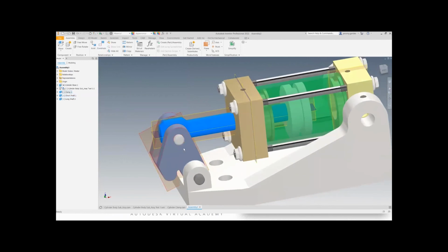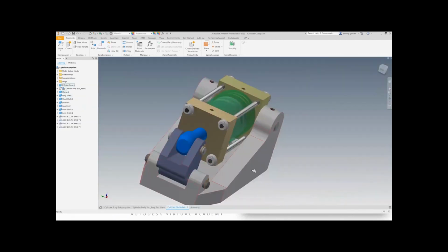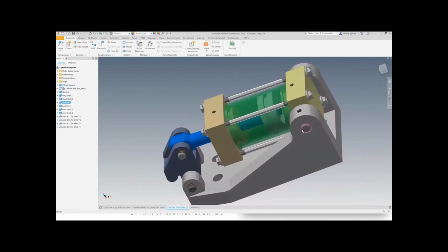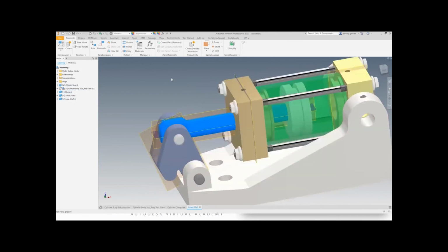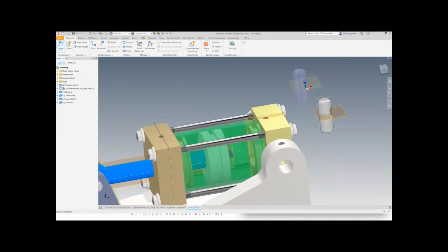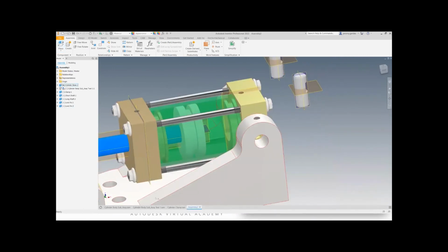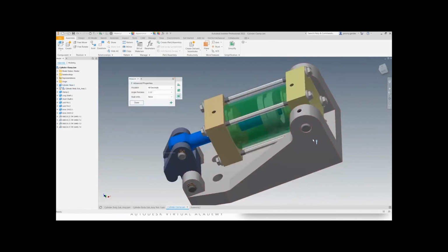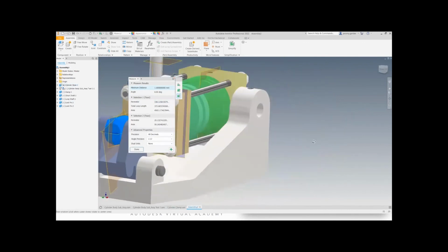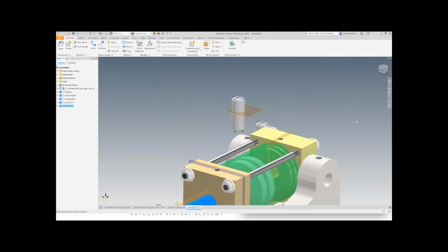So we have our 2 pins in. See the other components that they added. Okay, they have lock pins, they have clips. Check to see if there is any offset here. Oh, there is. So it's 1 millimeter out.